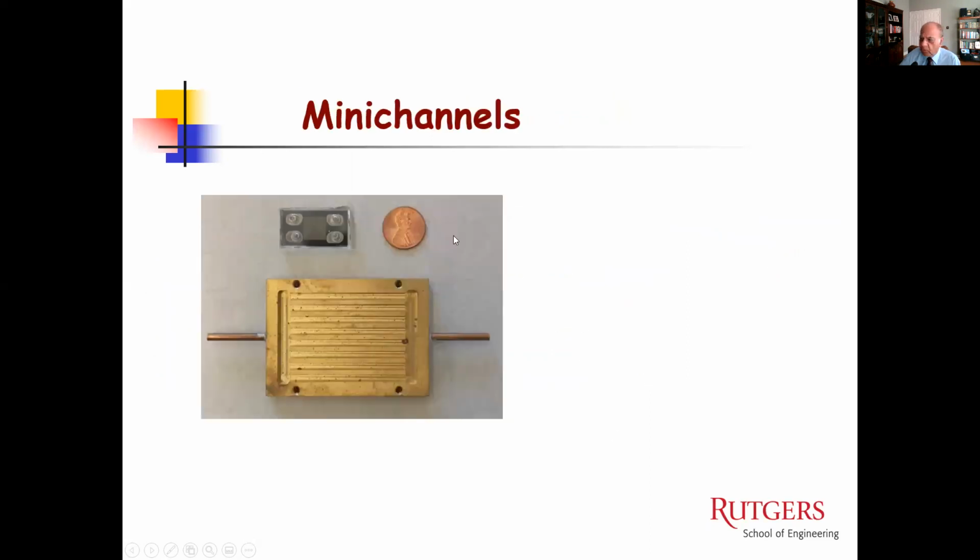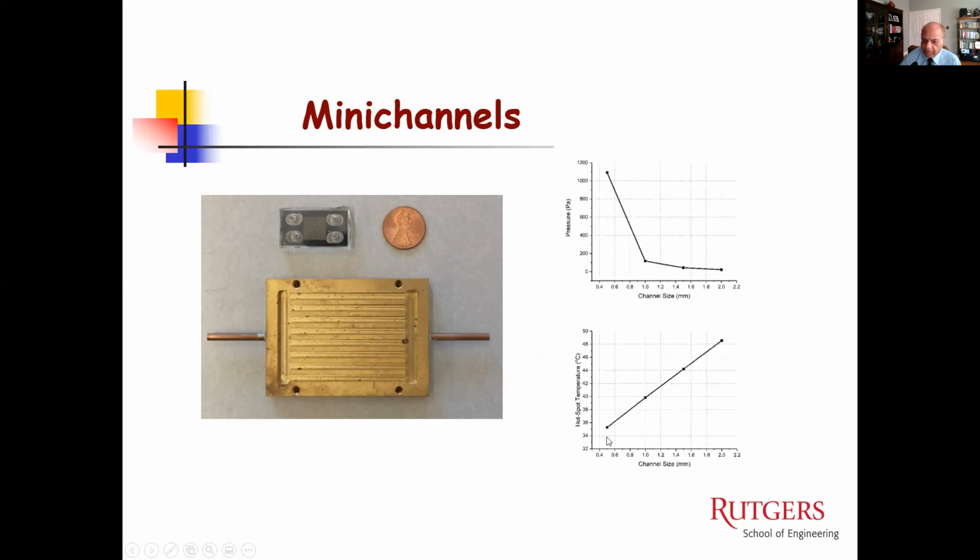The mini channels we looked at only to compare. And here's one of the experiments we did in mini channel. We found again that the pressures are really not much of a problem. Pressures are fairly low, and the hotspot temperature obviously increases as you increase the diameter, because then of course the heat transfer coefficient goes down, and as a consequence, the temperature goes up.